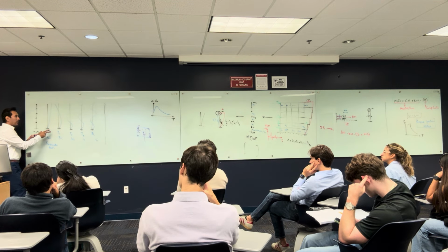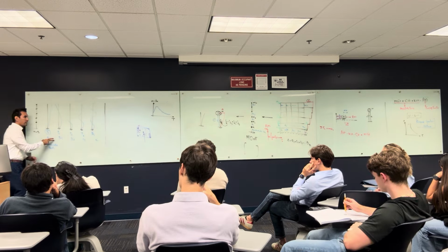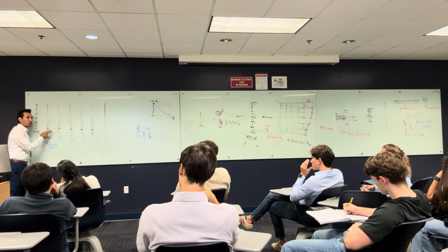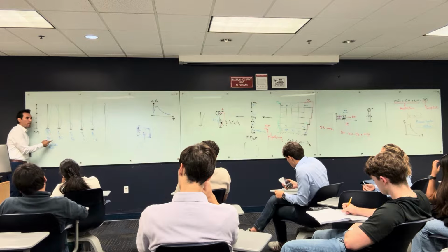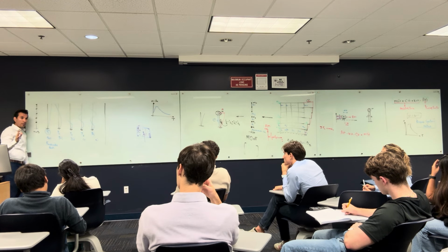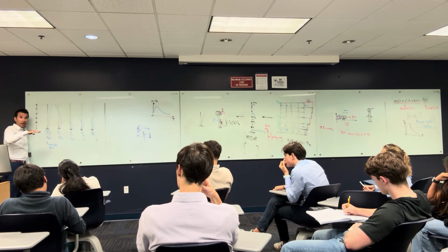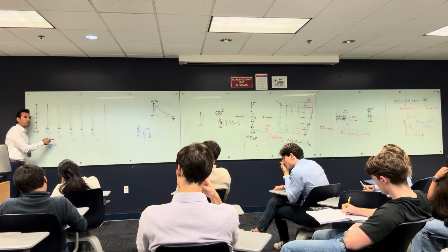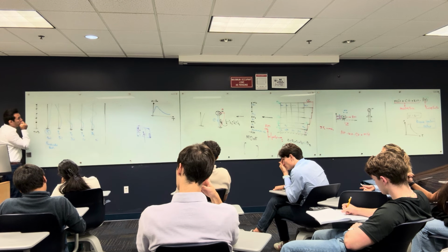But let's say that we made our system really good and this is our first degree of freedom. This first degree of freedom is gonna generate the fundamental period of the structure, and it has the most movement of the structure, and most of the masses, 90%, are moving that way. We try as structural engineers to make the first mode shape an X or a Y movement, and 90% of the mass is doing this movement. Okay? All right.